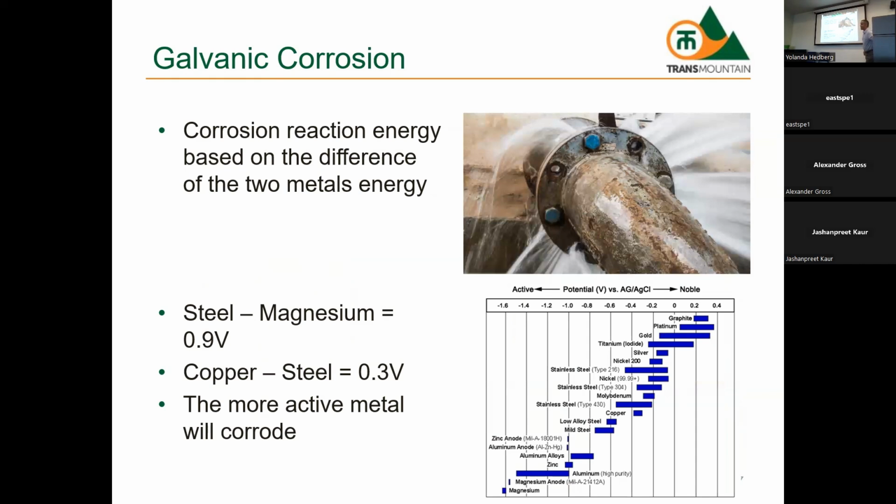So you fix this using galvanic cathodic protection. So you attach some zinc to the galvanized steel? Or... so we have steel, we have copper. We just choose a metal that's more electronegative. So in this case, I did designs for magnesium anodes to protect both the copper and the steel.